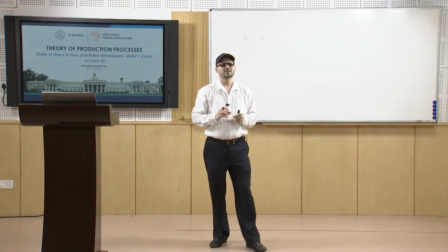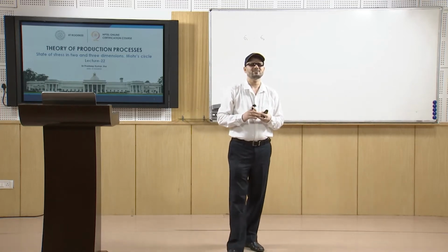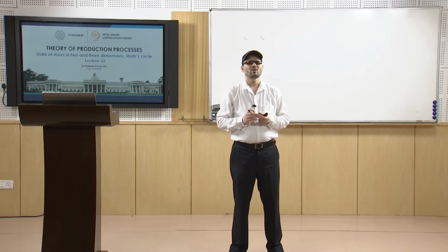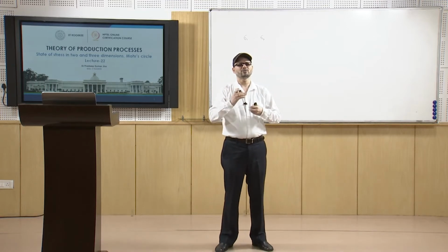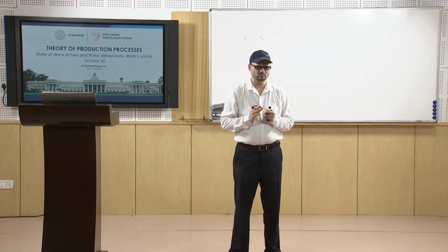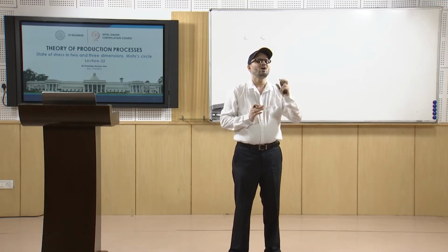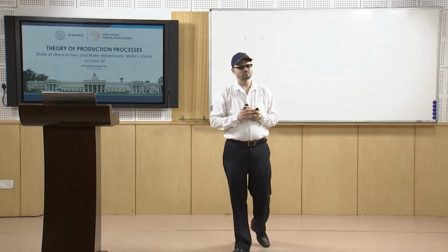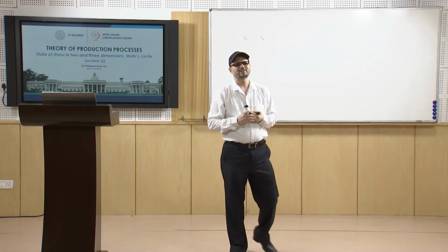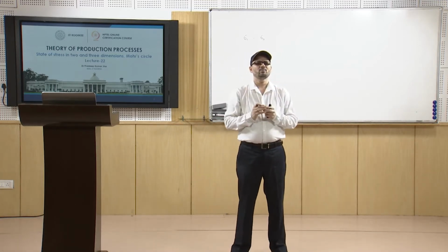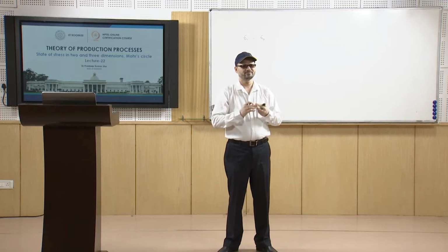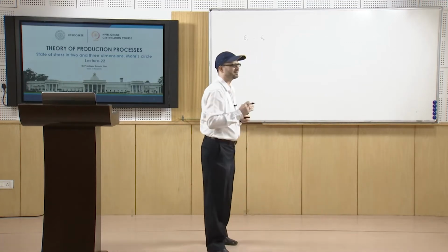Similarly, in the case of shear stress, the convention is that it will be positive if it points in the positive direction on the positive face of a unit cube, or in the negative direction on the negative face of the unit cube. Otherwise, if it is in the positive direction on the negative face of the unit cube, then it will be negative. That is how the sign convention is followed.